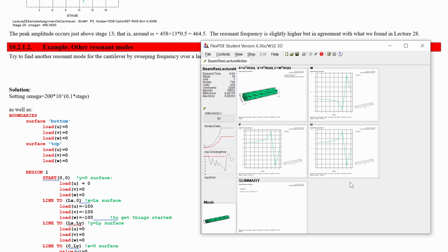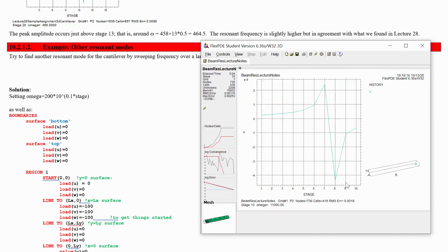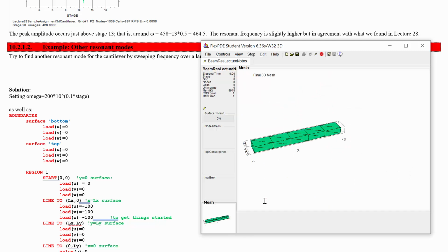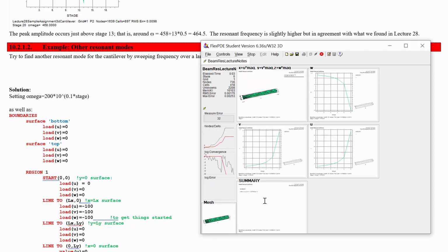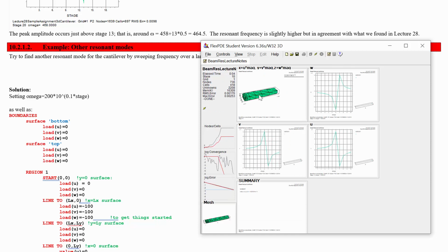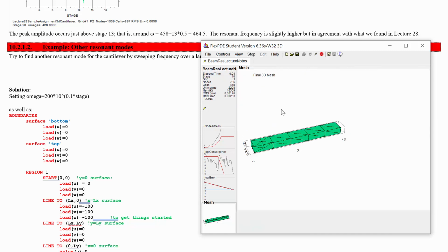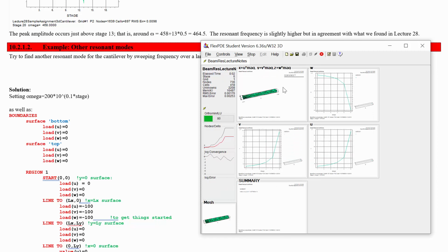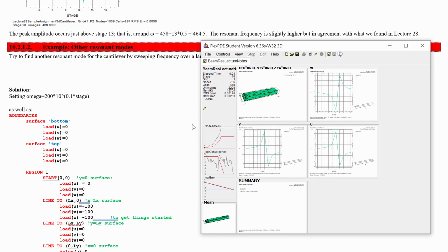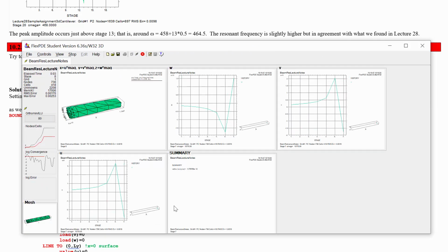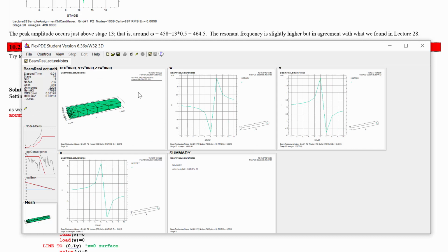Okay, we're rising up again, jumping around. So there we go. It's between 10,700 and 10,800. So 10,700, and we're going to add 10, in steps of 10, and see what's happening. Yeah, see this oscillating between the stretching and going to this sort of shorter, fatter one there? Yeah, that is the longitudinal mode we're looking for. Let's look at that again. Stretching, and then there. Maybe we can make this a bit bigger. There we go. So you could zero in on that and find the longitudinal resonant mode.